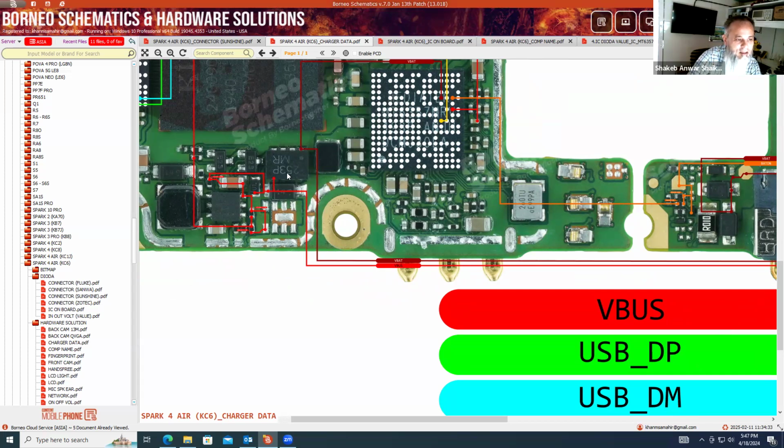So what is the connection between a VBus line and a VBAT line? Your VBus line will have a voltage of 5 volts, and your VBAT line will have a voltage of 3.7 volts, or maximum 3.8 volts, depending on the charge stored on the battery. So what is the interconnection between them, why have they given VBus and why have they connected the VBAT?